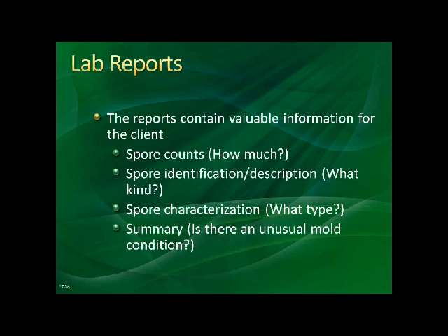Then we'll get lab reports. Once you pack everything up and you learn how to mark down your sampling media to send to the lab, which we'll teach you, you're going to send it to the lab. The lab is going to give you a report that's going to tell you how much mold was there, what kind it was, what type, and some of the labs will actually do interpretation and say that there is an unusual condition.